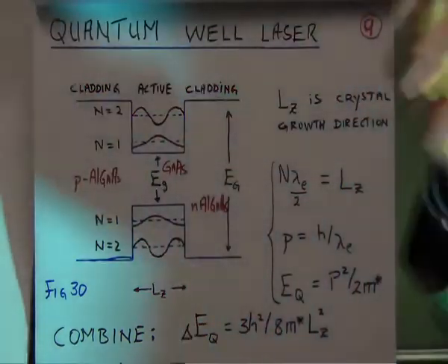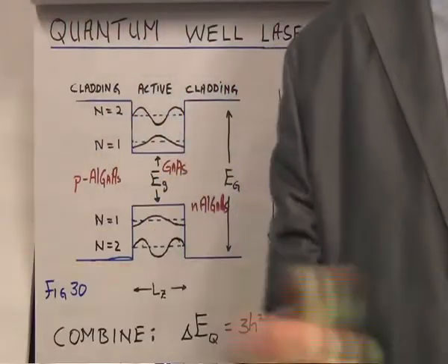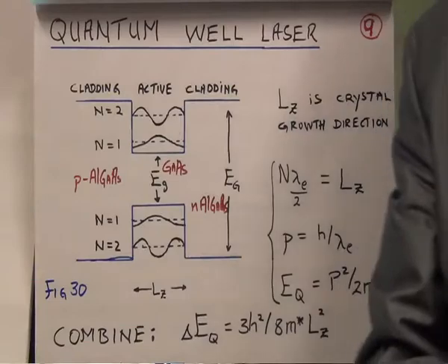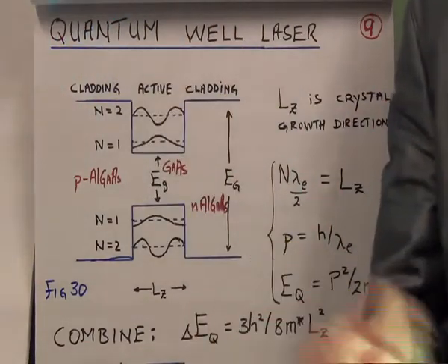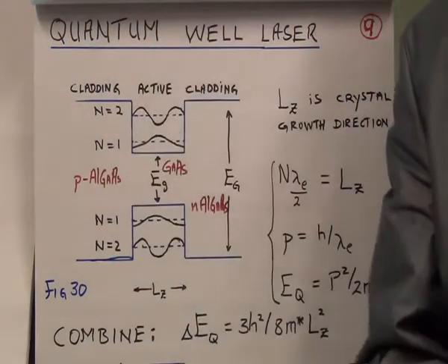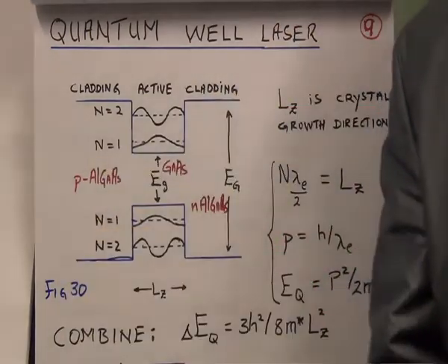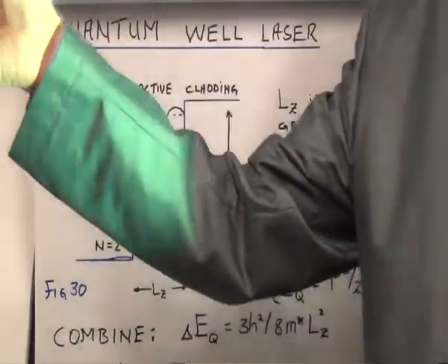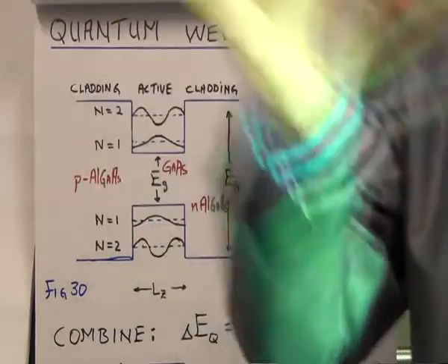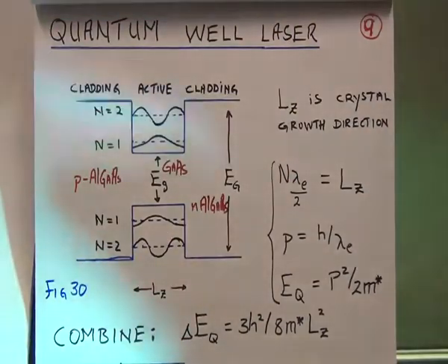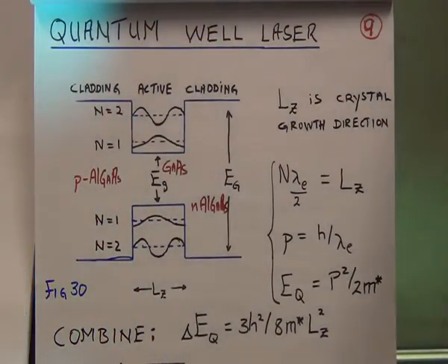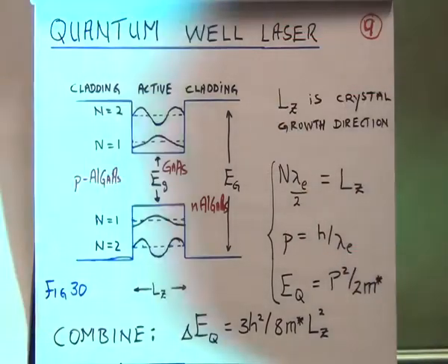We can't do it with the old-fashioned chemical vapor apparatus that I've talked about already. You need to use something like metal organic vapor phase deposition, MOVPE they call it, or molecular beams. You inject molecular beams onto the surface of the crystal. That's molecular beam epitaxy. So these new machines are able to grow nano layers that are required for this purpose.